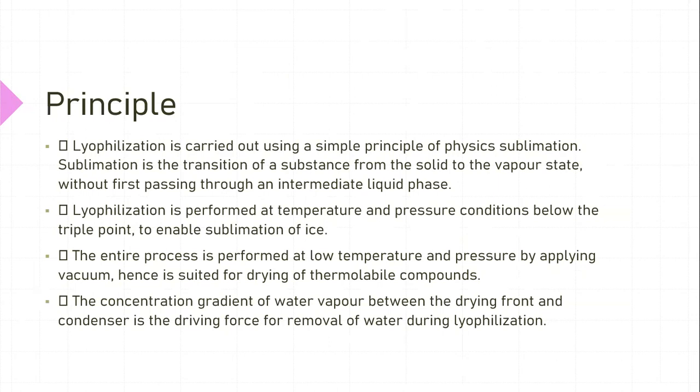Due to vacuum, the product dries at low temperature, which usually requires high temperature. But due to the applying of pressure, the product doesn't require high temperature for its drying, so the product dries at a lower temperature, whatever the requirement of your final product. The concentration gradient of water vapor between the drying front and condenser is the driving force for removal of water during